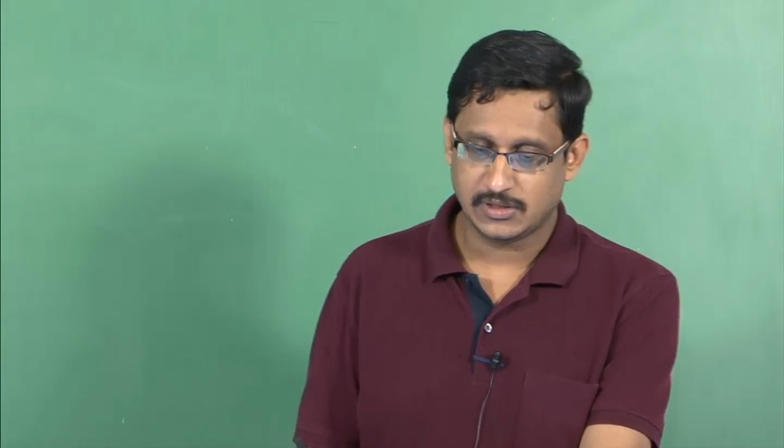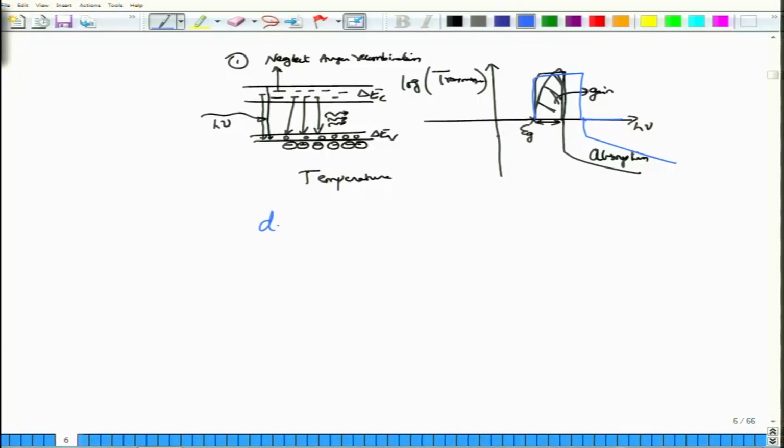Finally, the recombination rate equation is important, something that we had already written in the case of the rate equation for the simple, generic lasers that we considered. Here we need to modify it slightly. There the rate equation corresponded to the reduction because of spontaneous emission and reduction because of stimulated emission at the appropriate energy level, and so on.